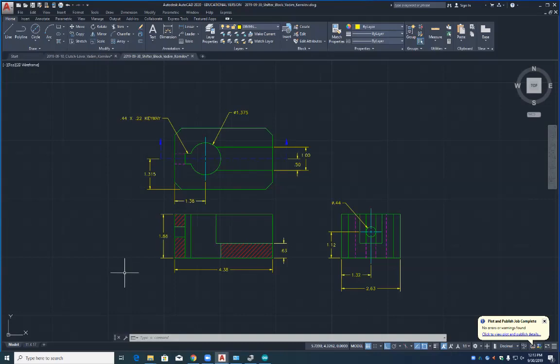Mike, do I want this 0.5 to instead be aligned with this? It should, because that should be a half inch down too, right? Well, this is a half inch from the center line. No, you don't do that. It's from your object. But when I type in 0.5, I think it by default takes it from here to here. Yeah, but if you went from here to here, 0.5, you put a half inch from your object. It depends on the order that you pick your points. Reverse the order.